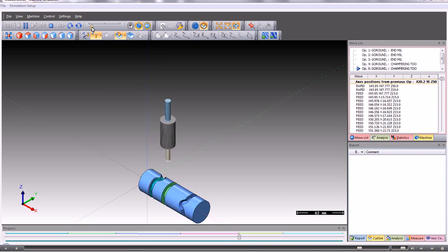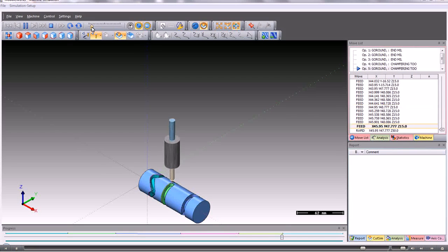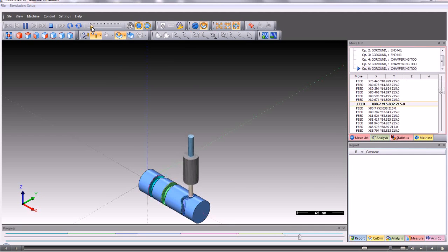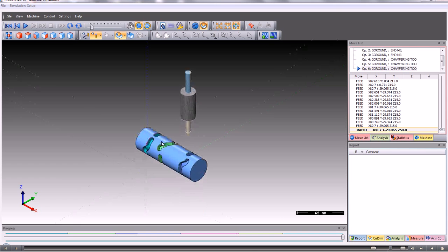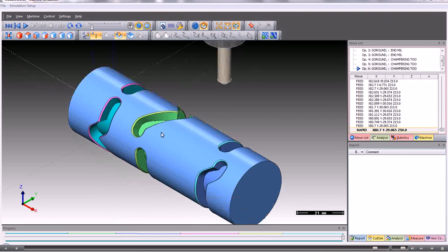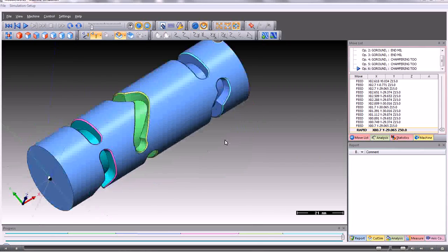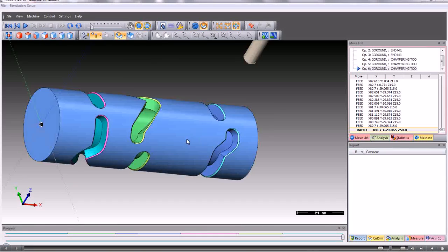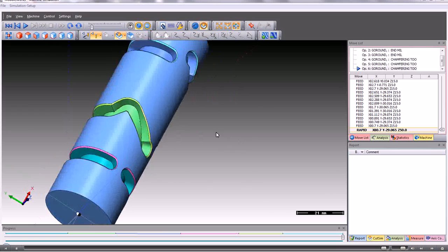So the nice thing about the way that we work on the rotary axis is, as far as the programming of it is concerned, everything that's available to you for the standard milling operations, such as area clearance, contouring, drilling, chamfering, all of those sorts of things, they're all available to you on the rotary axis. All that happens is that the post-processing software, which is the clever part, just wraps it all around a bar. So that's it. That's how we do that.